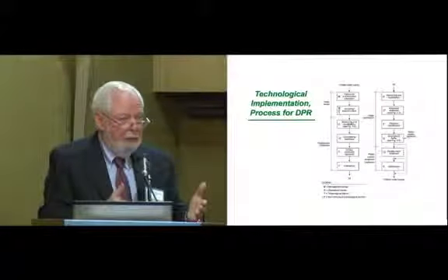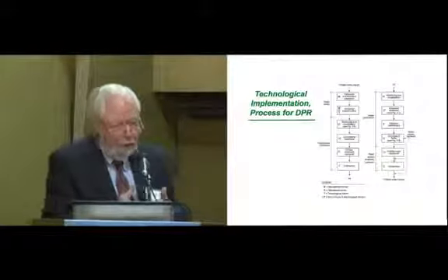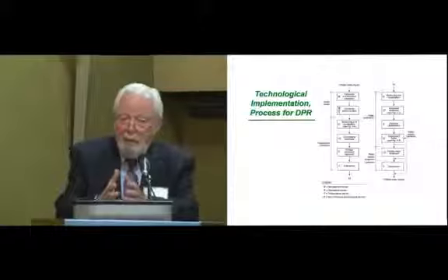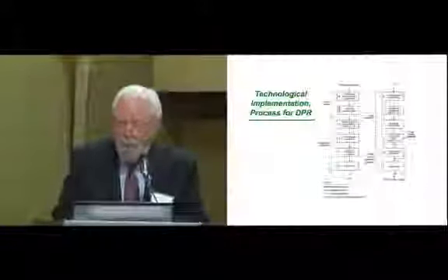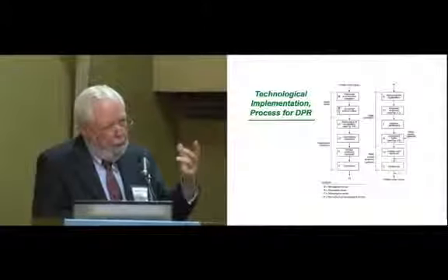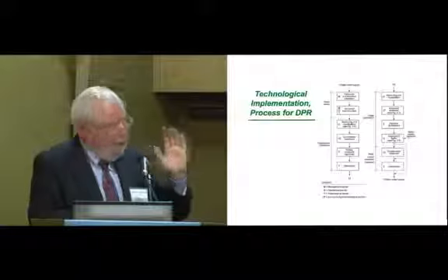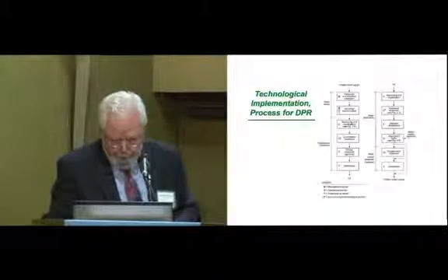Because the operators are there. And yet it screws up treatment plant performance something fierce. So as a minimum, if you just put in flow equalization, you would enhance the performance of your treatment facility. So we really need to rethink the way we design these treatment plants from the get-go, and especially as we think about producing potable water.